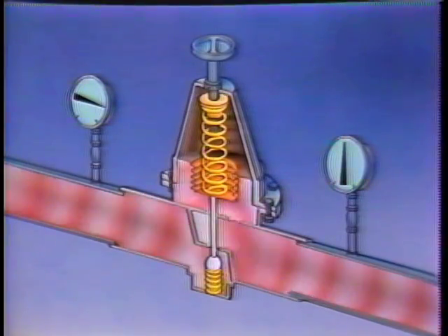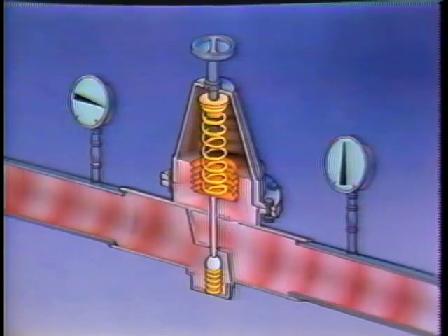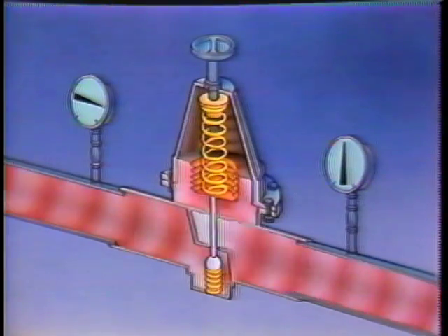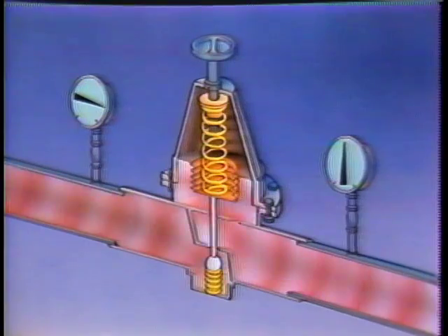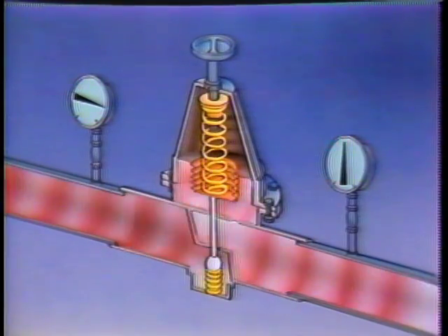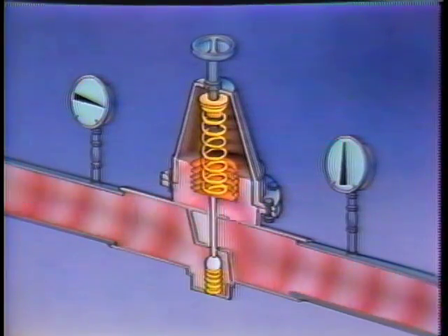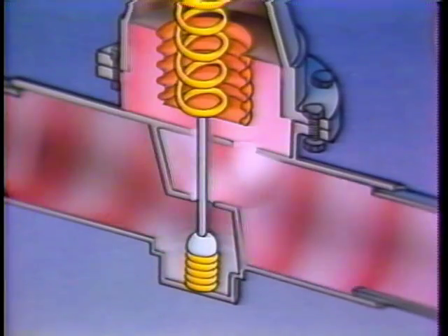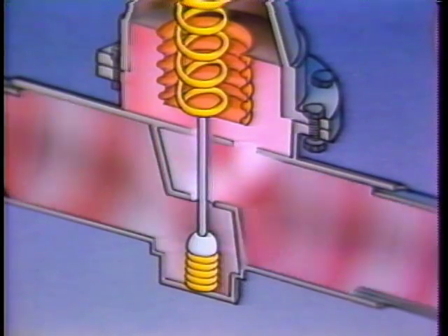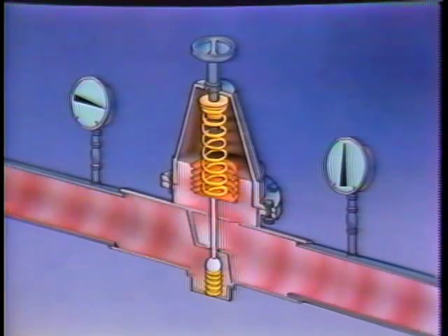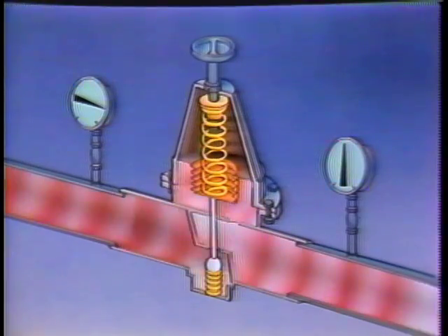In this way, the pressure is maintained at the set point while flow is reduced. When fluid usage again increases, the downstream pressure falls. The unbalanced set point force extends the bellows, pushing the valve further off the seat. The resultant increase in downstream pressure compresses the bellows until the forces across it are again balanced. Several variations to the valve are possible which allow it to be reconfigured for particular applications.